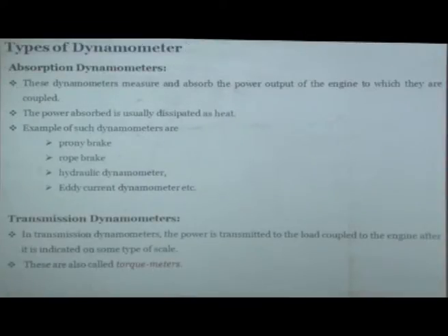Now what we will do is apply this. This is the basic measurement principle for whatever dynamometer. Now we will apply it to different types of dynamometers. So let's first understand the absorption types of dynamometer. Absorption type dynamometers measure and absorb the power output of the engine with which they are coupled,